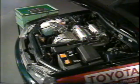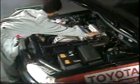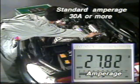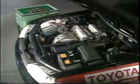If all voltage generated by the alternator is within standard, you can make your final determination of the charging system condition by doing a with-load test. In the with-load test, if the amperage generated by the alternator is at standard or below, you can assume that the alternator is at fault and inspect or repair it as necessary.